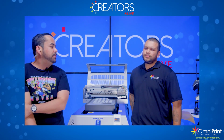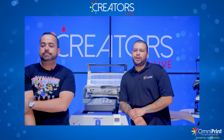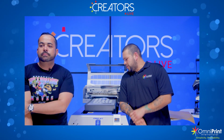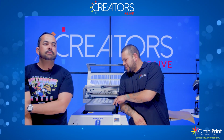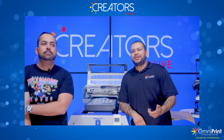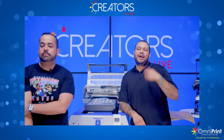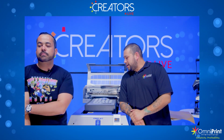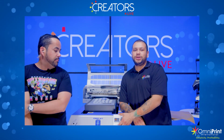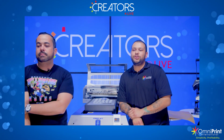What resolution are you printing these at? 2880 or 1440? 1440, yeah. With the heated platen, they had asked about speeding it up. One of the reasons for heating is that once you start to print faster, the ink has to dry fast enough for us to put the color and the rest of it on top, or even pack more color into it. So by having this heated platen, or even the ability to control the heat to go even higher, we are able to speed it up a little bit.